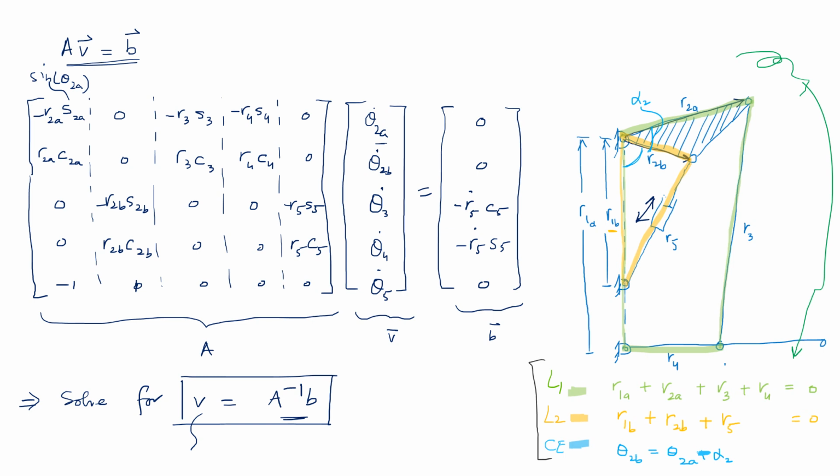So you did that, and from here you took the time derivative, constructed the vector loop equations in the polar form, and then you translated those into Euler notation, separated the real and imaginary part from each other, and then you constructed 5 equations using that, 5 equations for 5 unknowns, and because it was kind of a laborious task to simultaneously solve those, we have constructed this matrix notation over here to use the principles of linear algebra to solve these equations for 5 unknowns.